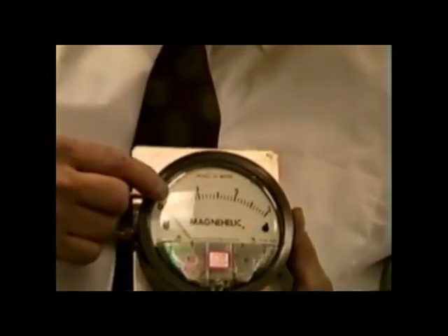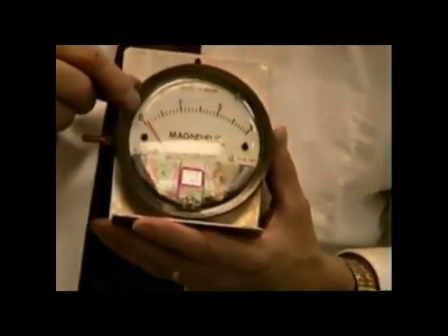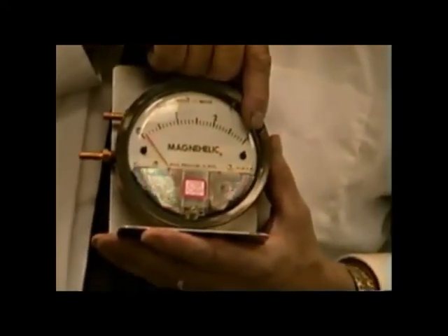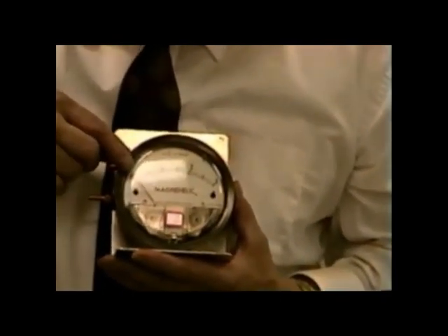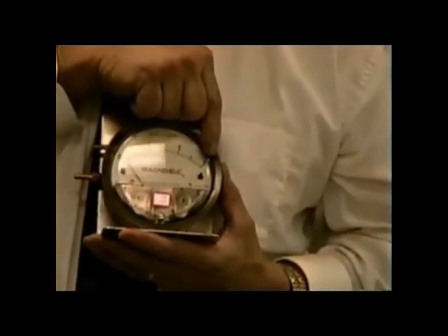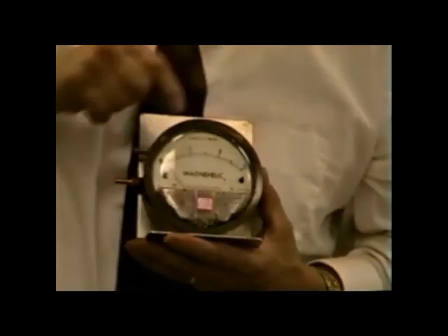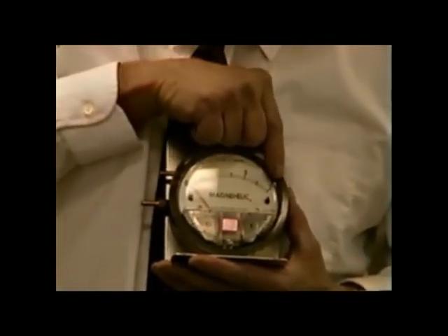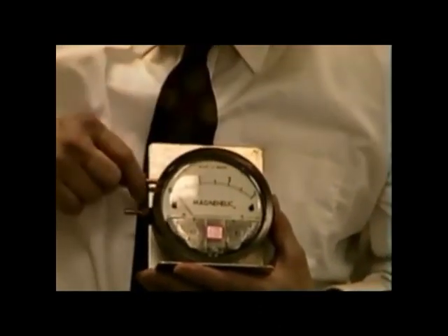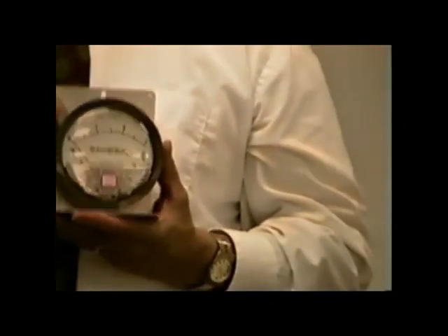By the way, magnehelic gauges also go from 0 to 3. We can have 0 to 2 inches. We can have 0 to 1 inch all the way, needle deflection. That's not in the handout. I'm just going through the magnehelic here. We can go from 0 to 0.5, very sensitive. And we can also go from 0 to 0.25, and that would be a draft gauge. But the point is, you could use a magnehelic gauge for checking gas pressure. Okay? Let's show you another method.